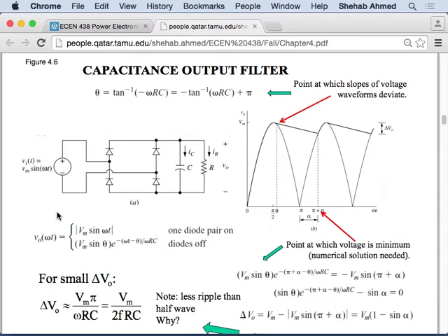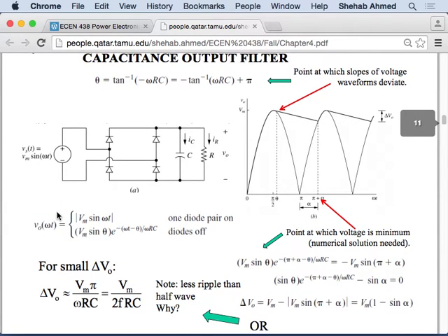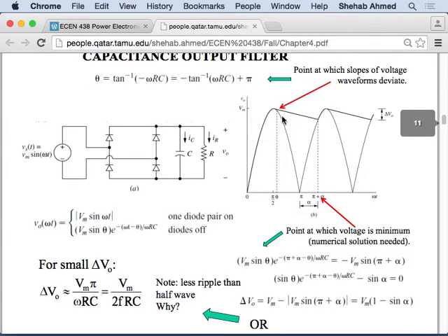Okay, so I want to wrap this up, and we spent the whole class on this. Just now, the equations that govern this. So now we know that this exponential meets the sine wave at this point. The book calls it pi plus alpha, or alpha angle after pi. So this is a point pi plus alpha. And we know that the capacitor voltage and the input voltage separate a little bit beyond the peak, at some angle theta, beyond pi over 2.